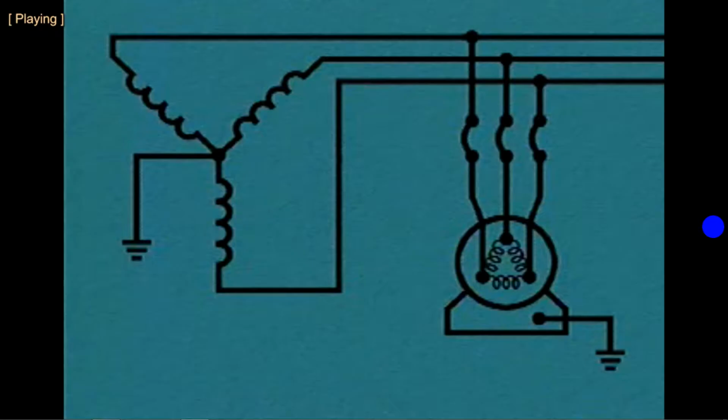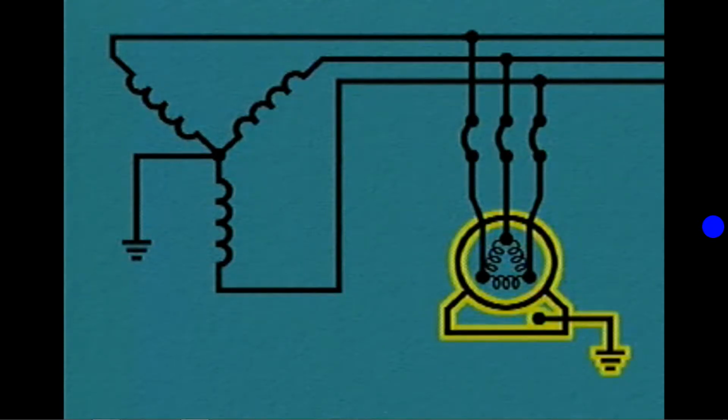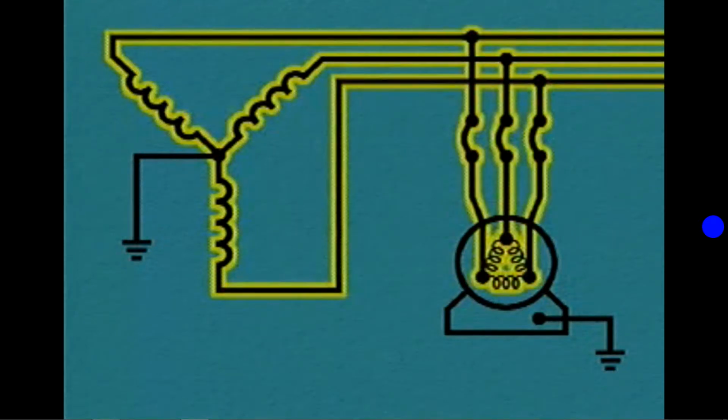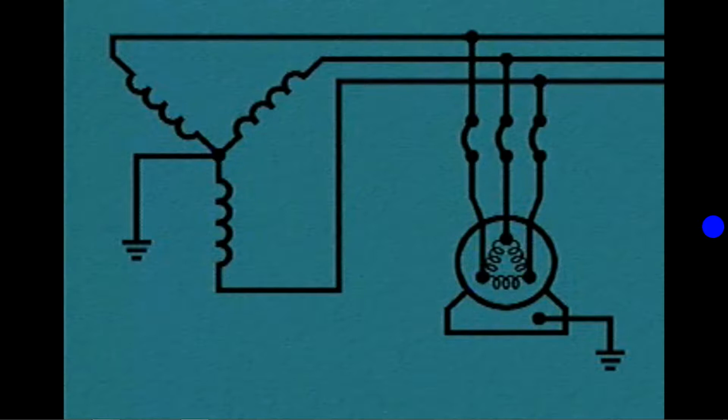For example, this is a simplified diagram of a hardwired or low-impedance grounding system. A low-impedance ground is an intentional low-resistance path for current flow to ground. The diagram shows a motor branch circuit with a circuit breaker and a motor with an equipment ground, and a secondary Y transformer that feeds the motor branch circuit. The transformer has a low-impedance ground connected at its center.